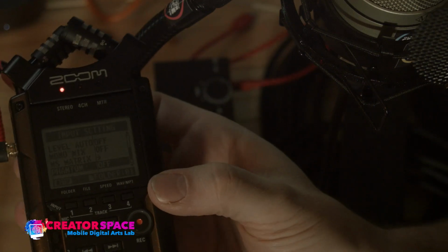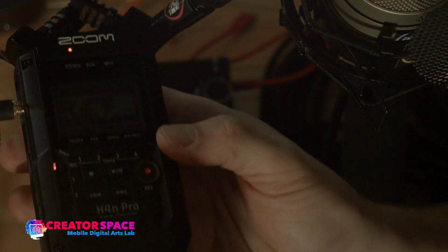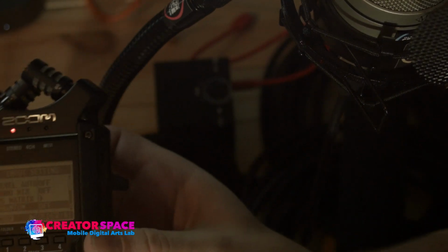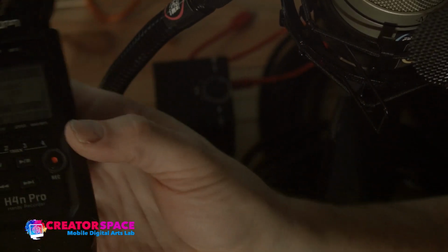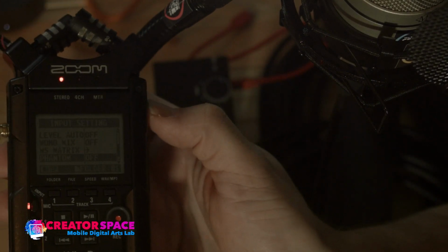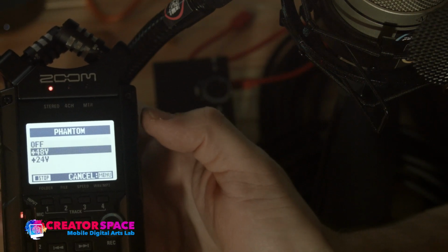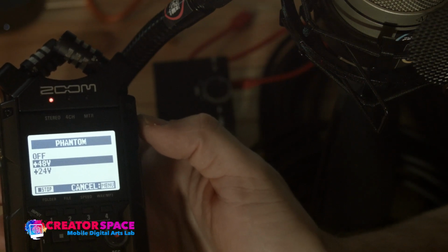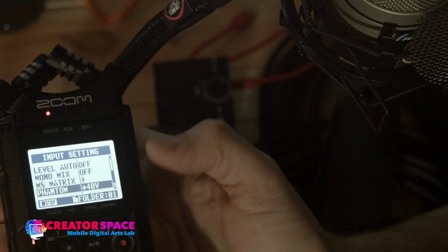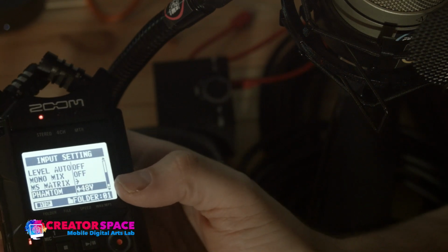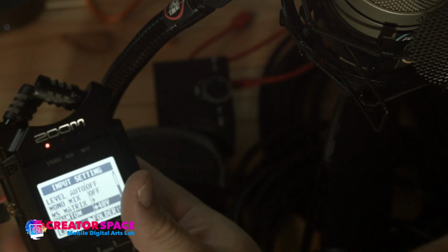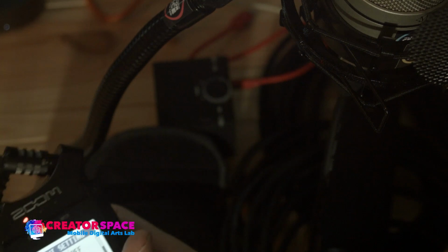I always recommend not having anything plugged in when we go to turn it back on. Turning it off won't do anything, but I like to always have the XLRs removed before I turn it back on so that there isn't any kind of voltage going into it. So again, I'm going to hit the scroll, and we don't want 24, we need 48 volts for the full phantom power that these microphones require. Press that, and now you can see it says it's on. And now we can plug in our microphones, and they will once again work because it does require that phantom power.